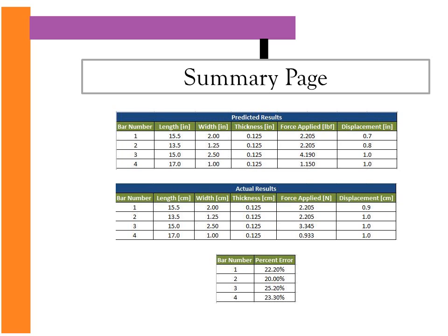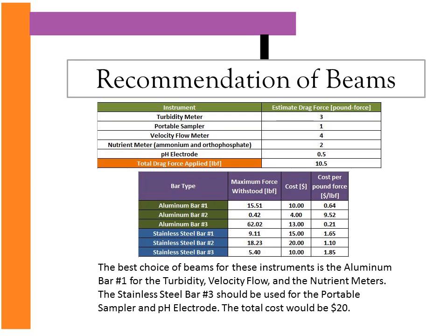First, any time an experiment is performed, human error must be accounted for. The measurements are only as accurate as the human eye will allow. The second and probably more prominent source of error is material deformation. Not only were the beams used by multiple groups of experimenters this year, they have also been used by engineering students in many previous years. After so many cycles of force being applied, the beams will start to reach plastic deformation. Because the beams are already deformed and the stiffness has already been decreased, the data is slightly skewed.